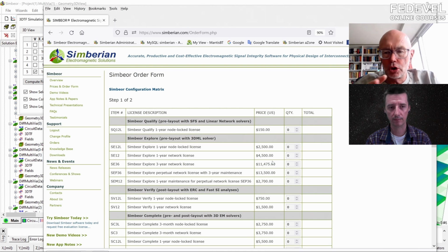In this ERC mode, it shows you some tips also. It creates reports, which I didn't show, where it guides you through what has to be done to fix the problem. And the whole idea of ERC is to guide you in the direction of designing predictable PCBs. So that's important. It indicates all the potential problems in predictability, potential problems in signal integrity or EMI/EMC. Unpredictability or loss of localization is a major thing.